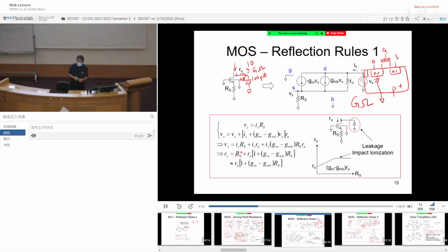But equivalent resistance is how much current draw at this point. So the two have to sum together, which means no matter what, eventually you are going to be limited by nanoampere. So nanoampere is how much? Gigaohm. Which means your resistance is going to be saturated. You can no longer go bigger. It's limited by the diode. Gigaohm. So in theory, I can cascade more transistors to get higher resistance, but in reality, nothing is free. Okay? Nothing is free.